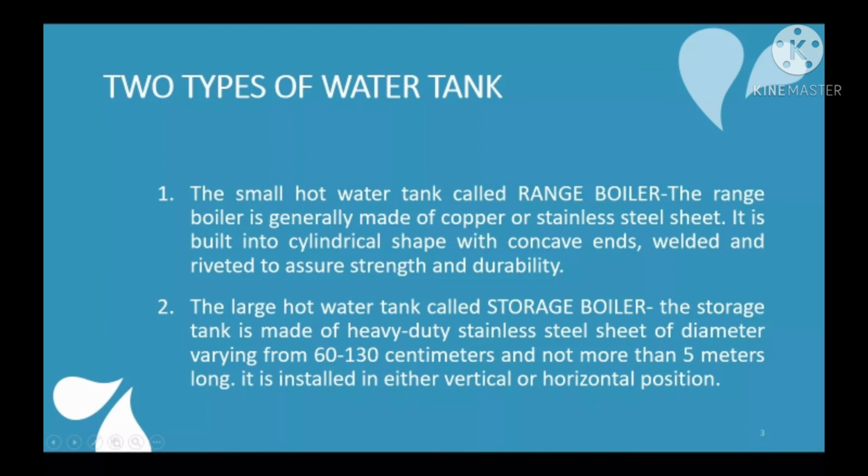Next is the large hot water tank called a storage boiler. The storage tank is made of heavy-duty stainless steel sheet of diameter varying from 60 to 130 centimeters and not more than 5 meters long. It is installed in either vertical or horizontal position.